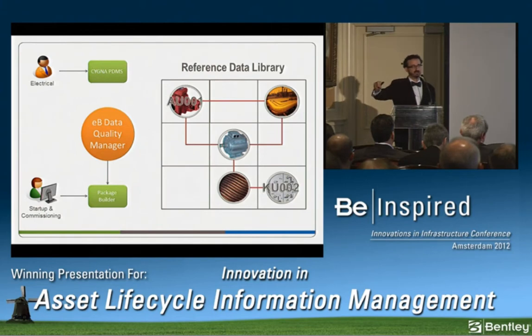They can assign specific assets to turnover packages through a review process, but because of the ontology present in the system, we can automate the assignment of many objects and many assets to packages based on the relationships. In this case, we have a pump that's connected to a motor that's on our process line. If you assign the pump to a package, we have a set of rules that says, well, in this case, for this type of system, you can automatically apply the same turnover code to the process line that they'll need to put in their package, and also the motor.